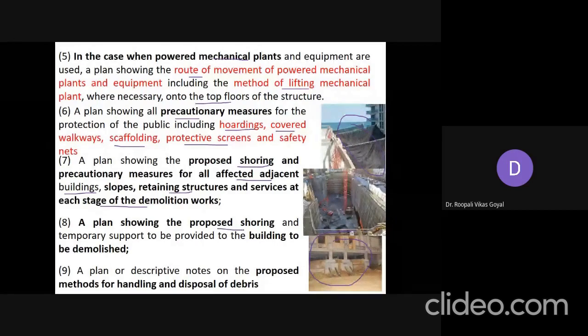As I told you, for both the surrounding buildings as well as the building that you are going to demolish. Proposed shoring means how you will support the existing building that you want to demolish, and the surrounding buildings, during this particular demolition. So all this shoring, that support work, you have to show. And a plan or a descriptive note on the proposed method of handling and disposal of debris.